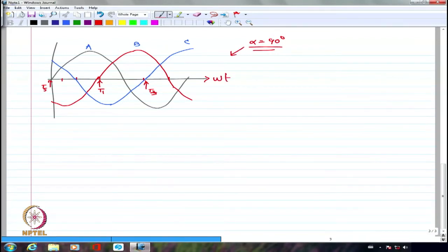Now if I try to look at it, again, for this duration, I will have 6 conducting. There is no opportunity for 1 to come in touch with 6 at all, because 1 is actually being fired here.